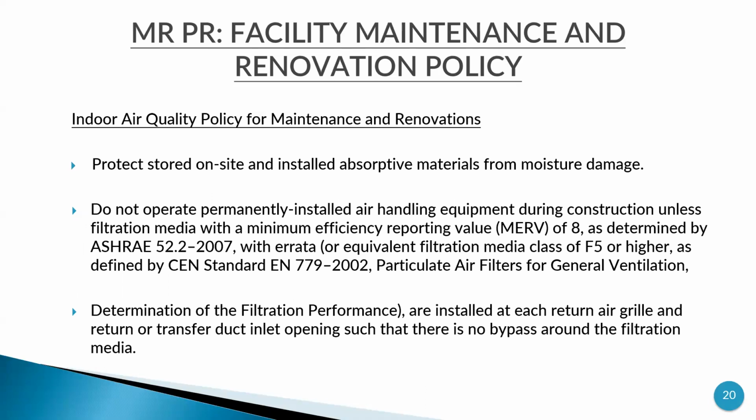What is the MERV of the filters you are using in your buildings? I don't know. You need to check that. How to check that? Ask the suppliers of the filter material, whoever is supplying, the MSDS sheet.